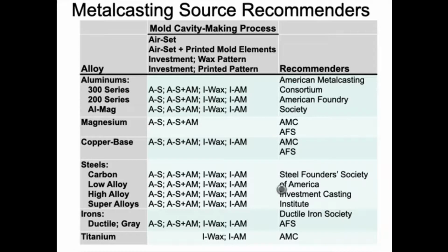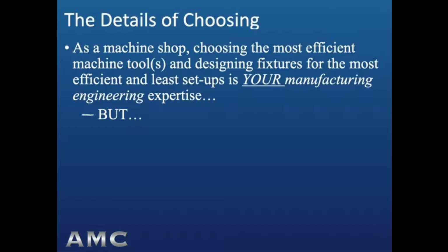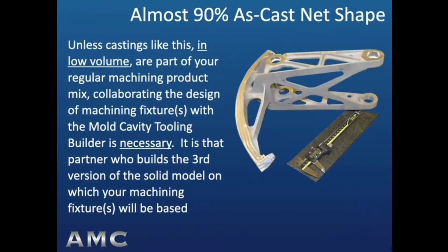As a machine shop, choosing the most efficient machine tools and designing fixtures for the most efficient and least setups is your manufacturing engineering expertise. But unless castings like this, in low volume, are part of your regular machining product mix, then collaborating your design of machining fixtures with the mold cavity tooling builder is necessary.